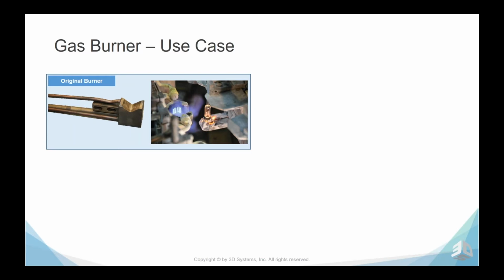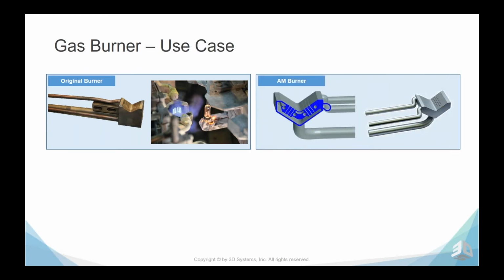Now, to make sure the nozzle holes don't deform because of the high temperatures, the burner is cooled using an internal cooling system. Now, due to insufficient cooling accumulated over several months of non-stop operation, tube attachment failed on the sealing plugs, or drill cooling holes came off. So obviously fixing these issues required lengthy and costly repair actions, which basically stopped the production line. So to reduce the downtime, a new cooling system was required.